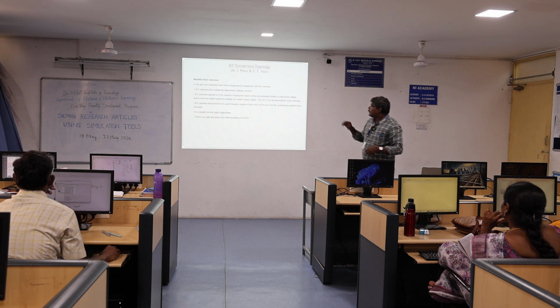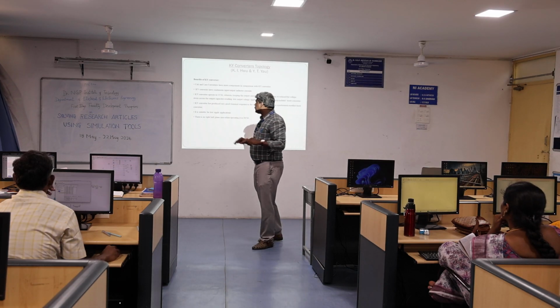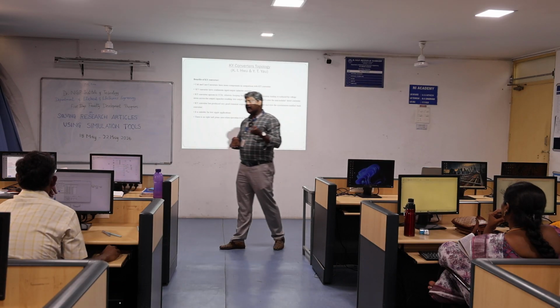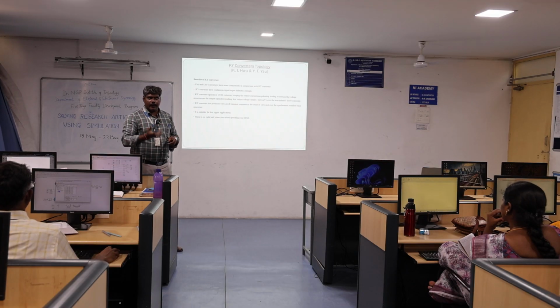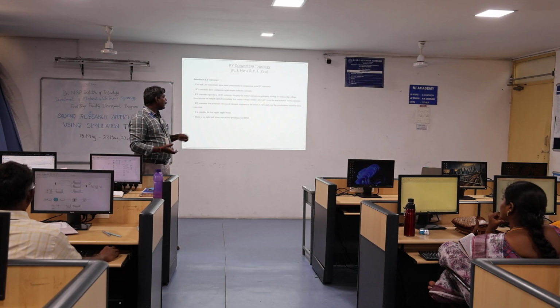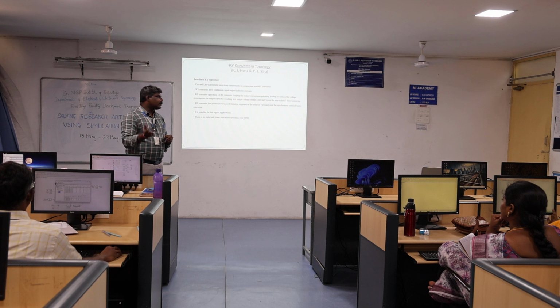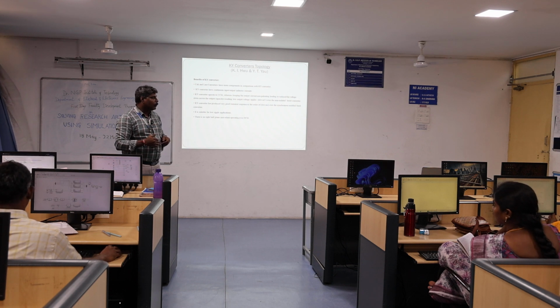So why do we go for these types of converters? We have different types of converters, Cuk converters and Luo converters. If you see the Luo converter and the Cuk converter, they have a larger number of components, in terms of storage components and devices, like switching devices and conduction devices, compared to the KY converter. This is one of the main advantages of this topology. Second, the KY converter has a continuous input side and output side inductor current.